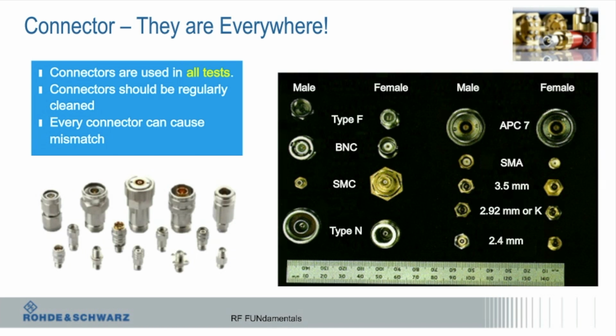So you might imagine that doesn't make for very precise tolerance. If you're going to connect it once and never again, it might be okay. I'm a VNA guy, so it doesn't work for me, but it's a very imprecise connection. It typically has undefined specs, so it's highly unrecommended, particularly with VNA measurements.